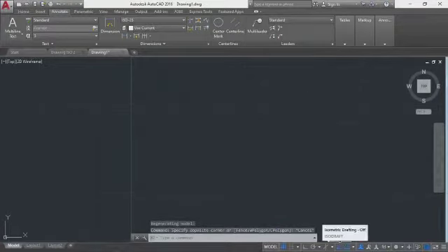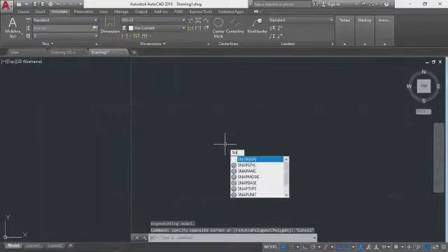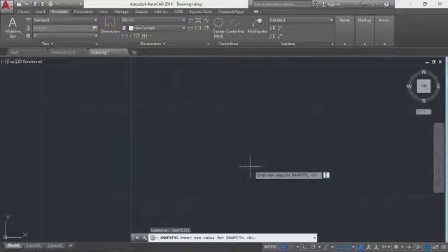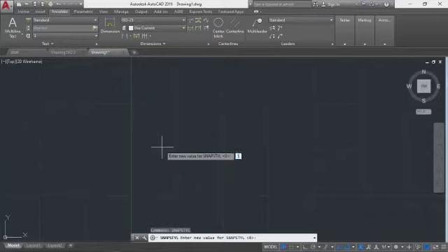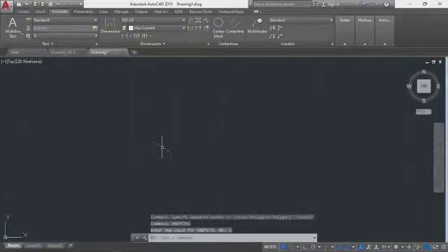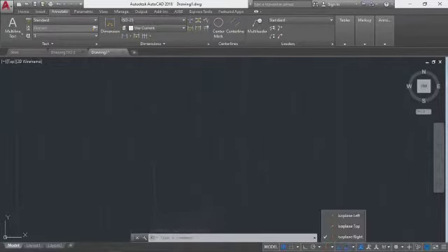So I want to use snap style. You click on it. Good. Now you click 1 to put it on isometric. Do you see that? Now you can use F5 to change your direction, or you come over here to change it to top, left, and right, depending.